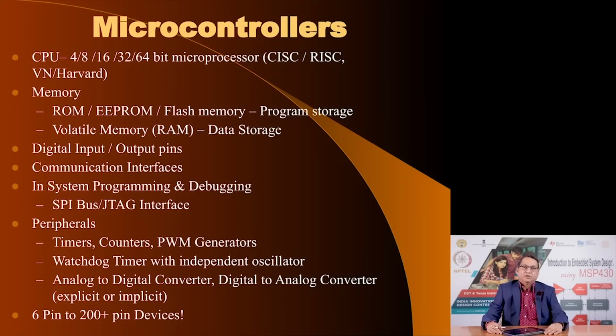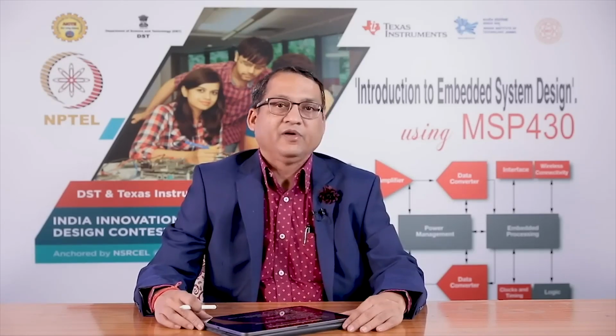Microcontrollers offer general purpose pins, which can be programmed to behave as digital inputs or as digital outputs. They often have several communication interfaces. What we mentioned, intra device or inter device, it may have UART, it may have LIN, it may have CAN, it may even have USB, and we will see what all our microcontroller that we are going to use has.